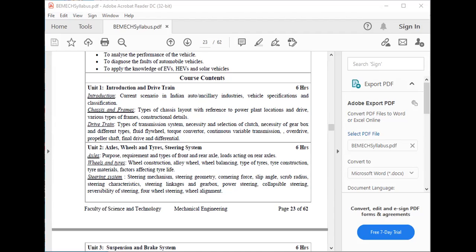If we see the components, the primary component is the flywheel, then clutch disc. See here, this is the flywheel which is in yellow color, then clutch disc which is in green color here, then clutch cover is available, then this is the release bearing, clutch release bearing hub, this is the clip, okay, this is also clip, clutch release fork, all these are the components. Single plate clutch working, the diagram shows the pressure plate.